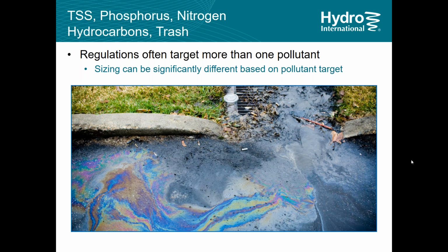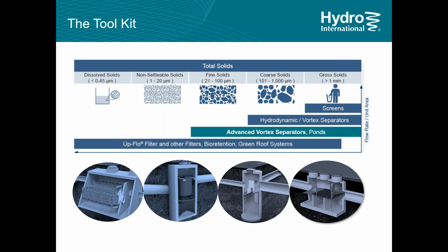And as you can see, stormwater isn't discriminatory. It will carry whatever pollutant we throw at it and bring it down into the storm sewer system and into the receiving waters. So the BMPs that we put in place have to deal with not only a range of pollutants, but quite a range of stormwater conditions, flows, and that sort of thing. So they're asked to do a lot for a passive system.